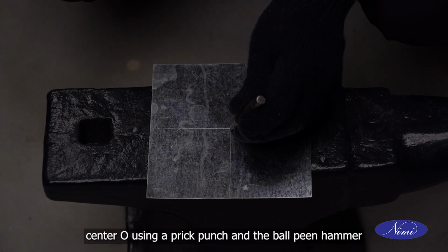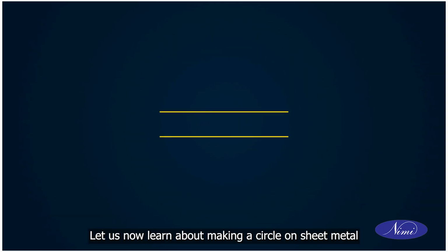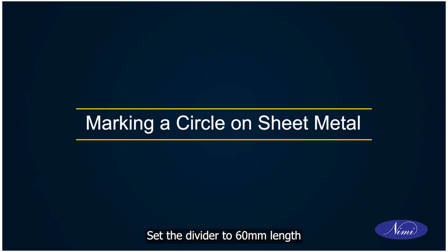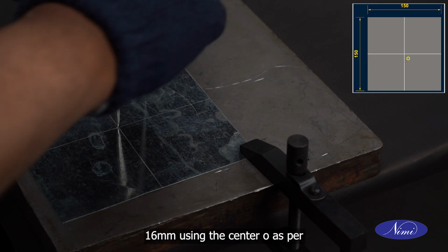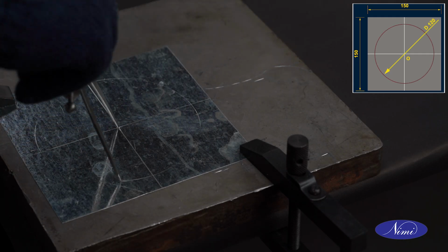Witness mark the arc center O using a prick punch and a ball peen hammer. Let us now learn about marking a circle on sheet metal. Set the divider to 60 mm length using a steel rule and mark a circle of radius 60 mm using the center O as per the drawing.